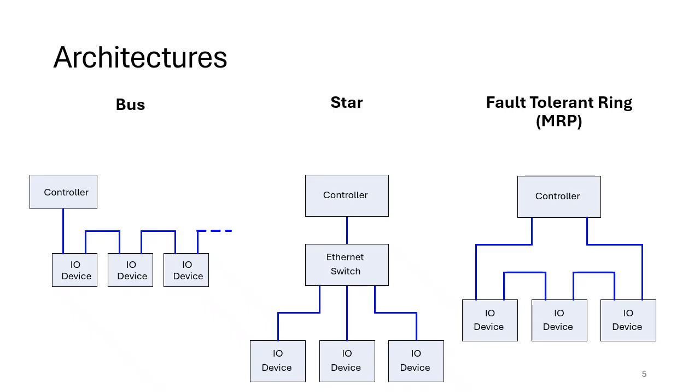And then on the network you have a media redundancy controller, or MRC, or a master, MOM rather. MRC is actually the client, so media redundancy master. What happens is the media redundancy master detects the returning packets, and when it receives them, it stops sending them back around the network. As I mentioned earlier, if you did a ring with normal Ethernet, there's nothing to stop the packets being transferred multiple times, and then that can cause an overload on the network within a few milliseconds because the packets just are sent and resent and resent. So the media redundancy manager, the MRM, makes sure they're not resent, so that gives you your fault tolerance.